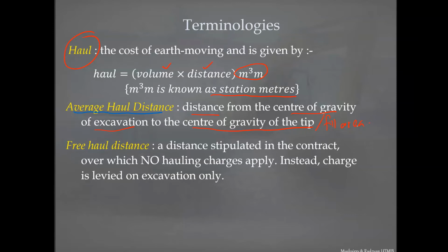Alright, and freehaul distance is a distance stipulated in the contract, and it says that if you transport soil within that distance, they won't charge you for hauling. So there's no hauling charges. You only have to pay for excavation charges. It might be a few hundred meters, depending on what the contract says.